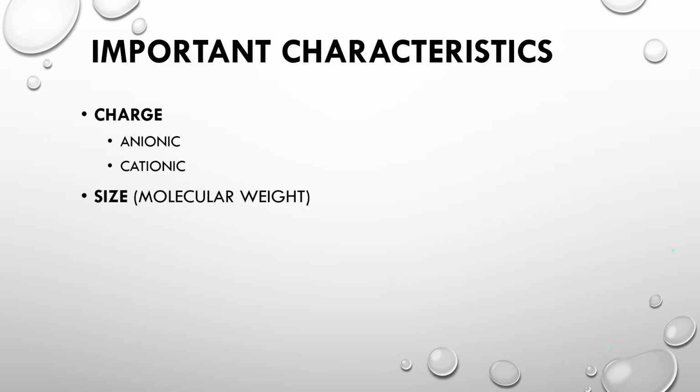Now this is really important because anionic polymers are negatively charged and they're safe for aquatic organisms. Fish and other organisms have negative charge on their gill surface, and you're probably familiar with the concept that opposites attract and like charges repel. Negatively charged polymers will repel against the negative charge on the gill surface of fish, and they're very safe and not going to cause toxicity to fish at the amount that's going to be effective for taking out sediment and metals and things like that.